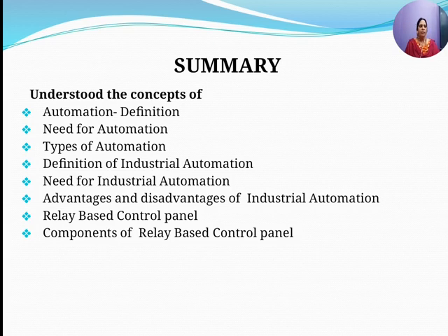The advantages of relay-based controls are you don't need to have knowledge of programming concepts. They are used for simple systems. They are large in size, which is a disadvantage, and components are connected directly, that is hardwired. They are used in simple applications with simple control logic, which do not require frequent alterations and modifications. The components of a relay-based control panel are electromagnetic relays, timers, contactors, fuses, MCBs and indicators.